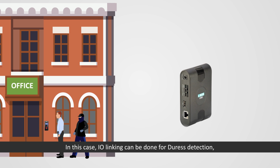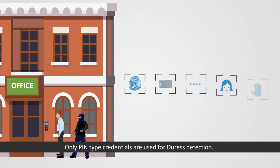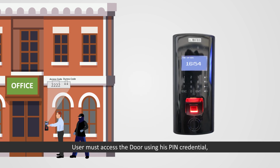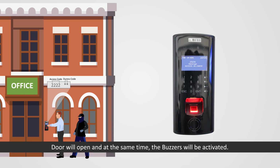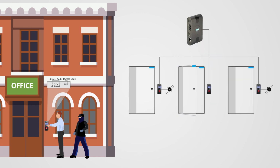In this case, I/O linking can be done for duress detection, connecting buzzers to panel doors through the aux output port. Only PIN-type credentials are used for duress detection. The user must access the door using his PIN credential. Press the arrow key, then enter the 2-digit duress code, and press enter. The door will open, and at the same time, the buzzers will be activated.